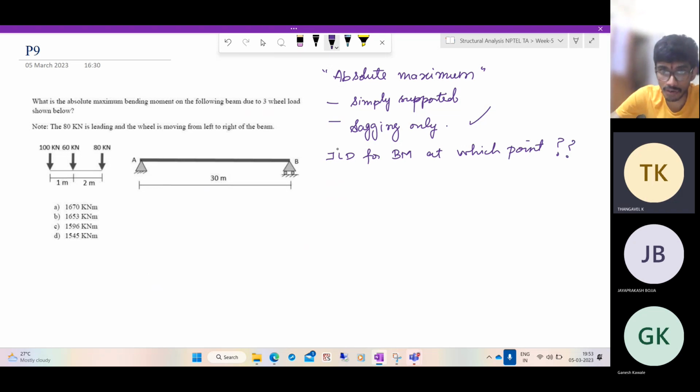We can if we know the point and the function we want to find, such as the bending moment at point C located at some distance from the support. If that is not specified, in general we cannot draw the influence line diagram. But let us use our intuition. In a simply supported beam, we'll get the maximum bending moment when the load is somewhere in the middle region.